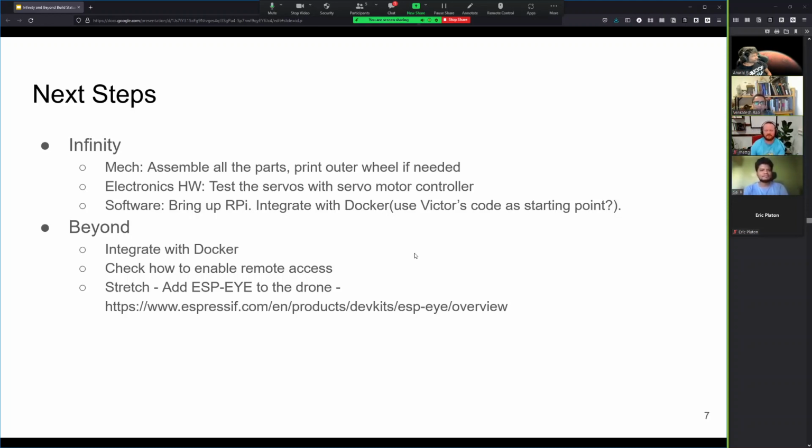Maybe if I have. Yeah, that's why I was curious about weights. If you're even thinking of attaching a separate battery, that's a lot of weight. Batteries are quite heavy, even a small battery. I think you can. If you look at the batteries that are available in mobile phones, in the old Nokia mobile phones, they are quite light. Yeah. And you can have small 1 inch by 1 inch batteries. And the battery on the drone itself lasts for around 13 to 15 minutes. That's it. So one flight is around 13 to 15 minutes. So if I draw from the battery on the drone itself, maybe it reduces the flight time to around 10 minutes.